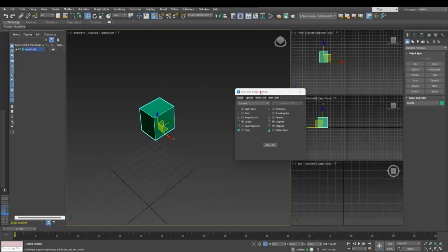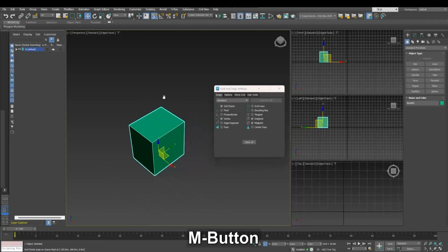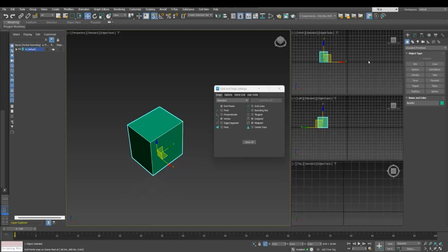Now, to keep this on, say I want to model, or I want to have another square box on top. On your right hand side is a Create panel. So in Create, you've got your geometry and your shapes. Let's create another box. Click Box.